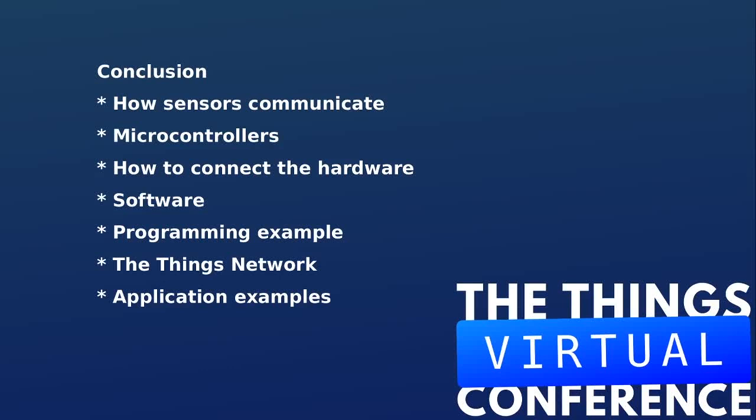And then we looked at the software, the IDE for flashing microcontrollers. And we also looked at installing hardware support in the Arduino IDE. We looked at some programming examples where we read out the data from the sensor into the microcontroller, saw the sensor data in a terminal in Arduino IDE called a monitor. And we actually managed also to see a program from the microcontroller sending data into the Things Network.